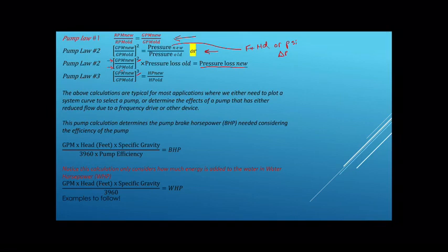So it's huge, the amount of reduction in horsepower that will happen with fairly small changes in GPM. So it's to our advantage to try to understand that. That's the whole basis of why we use frequency drives in systems. In your commercial applications, you can save customers a significant amount of money if you really understand that.